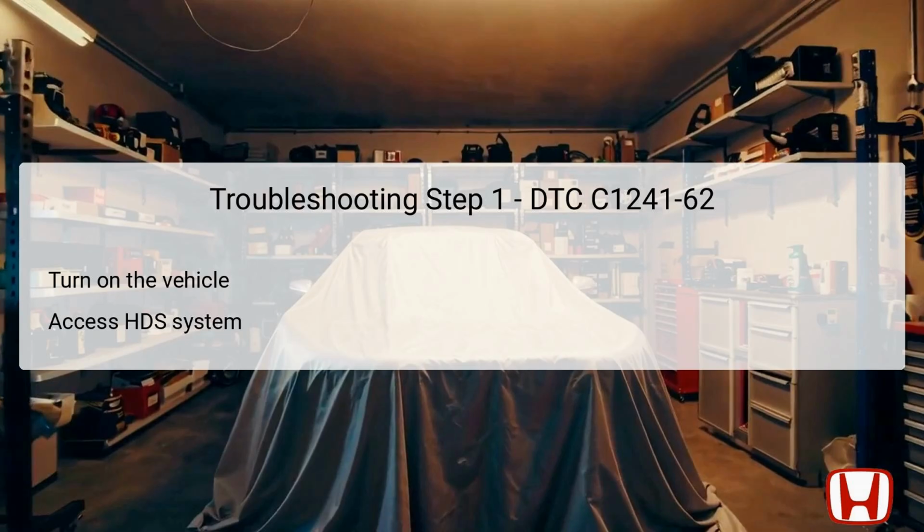When the HDS is accessed, it provides valuable diagnostic information about the vehicle's electric vacuum pump system, including the status of the brake booster pressure sensors. It's crucial to follow the diagnostic protocol outlined in the service manual for the most accurate results.